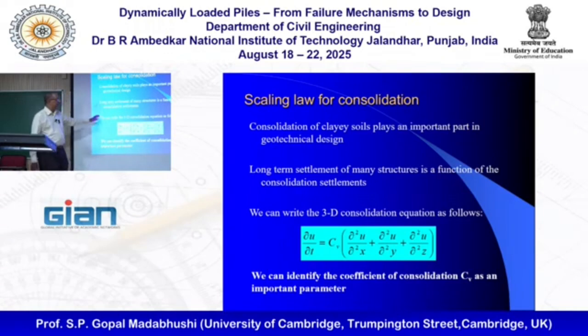However, the theory for consolidation is quite mathematical, very easy. When you put a load, if the pore pressure increases, you call it U. So dou U by dou T is the rate of change, or time change, of the pore pressure. You link that using a coefficient of consolidation to the second spatial derivative of U in X, Y, and Z directions. Great. And we can solve this PDE until the cows come home.